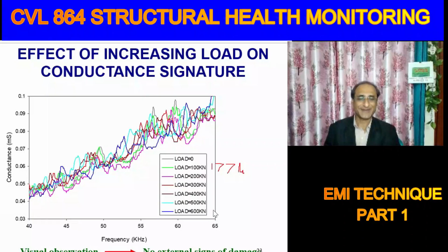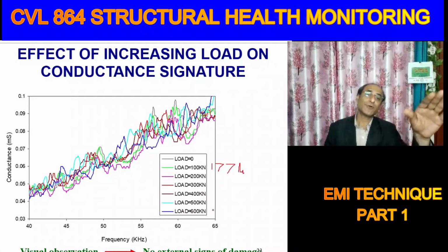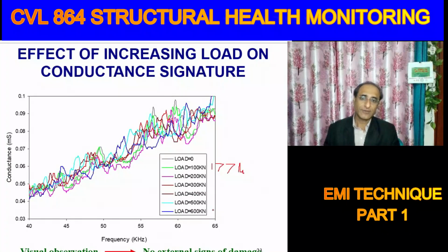Yes, so Young's modulus also undergoes change as we are doing the loading. And now remember, this is a hysteretic loading. It's not in a single go. We are loading to a particular level and then unloading. Next cycle we are doubling the load and again unloading. So Young's modulus would gradually reduce. So our calculations of the strain would not be that accurate, but even if we assume that the Young's modulus remains the same, what value are we getting for 600?